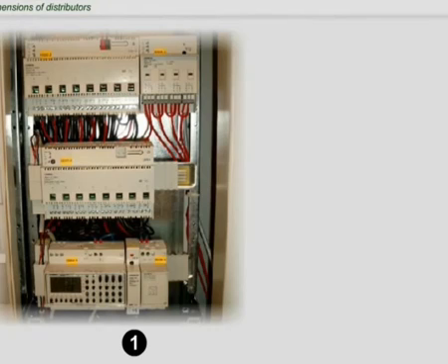One DIN rail is subdivided into 12 units, whereas the width of one unit is 18 mm. The mounting space of EIB devices can be calculated by means of a formula. If you divide the number of all consumers by the factor 8.5, you get the number of all required DIN rails. Consumers are, for example, lamps, switching sockets, blind motors and heating valves.